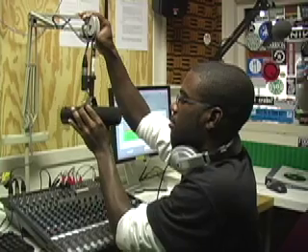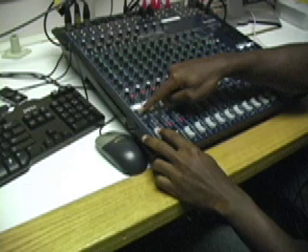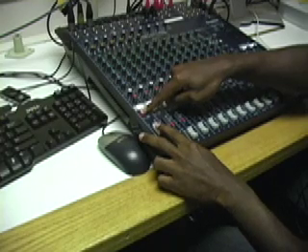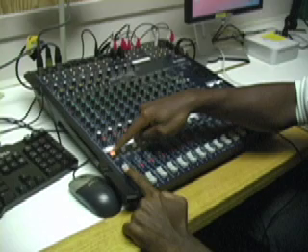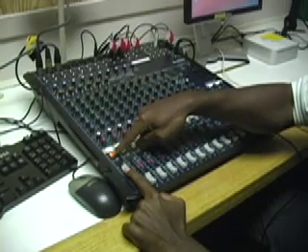Our studio microphones are controlled using the mixing board. Make sure when you use them you are approximately 6 inches away. This button must be lit with the volume up in order for the audience to hear what's coming through that channel. If you make any adjustments while the button is on, the audience can hear them. If, however, you make adjustments while the button is off, the audience cannot hear them.